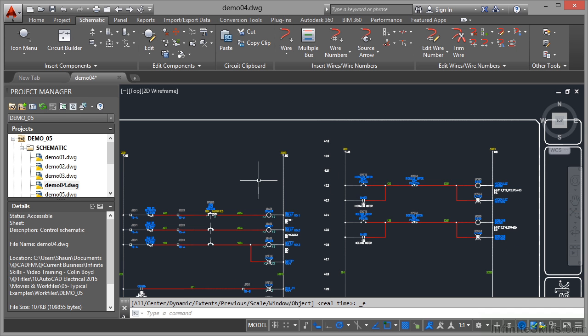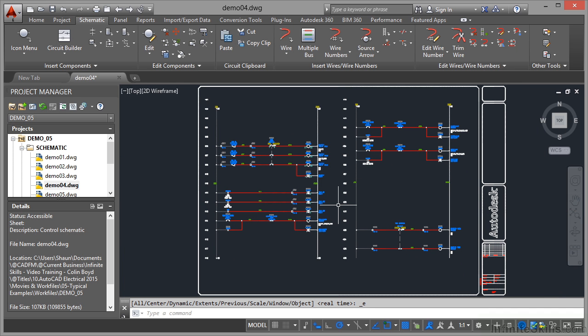So it allows you to obviously work with these tools such as logic ladders by placing the components going across from one side of the ladder to the other as rungs. And the good thing is each rung is numbered. You have a reference. Point to point, you're literally drawing the circuit as you go from one point to the next point, using what they call connectors to link into the main wiring. So that's another typical AutoCAD electrical drawing, this time a logic ladder drawing.